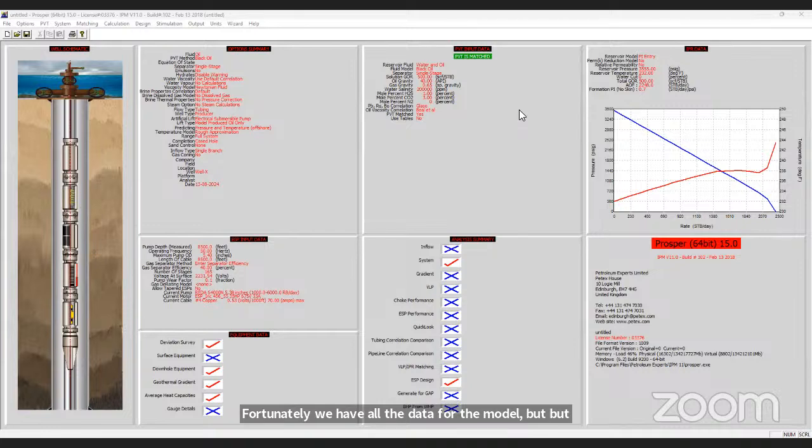Challenges arise depending on the pressure losses. Basically, let's say if I have high gas, it will cause gas interference to the pump system that I installed. If I have more gas, the system will not operate at all. So yes, transition between different flow regimes will cause some problems in the completion equipment and lifting systems.